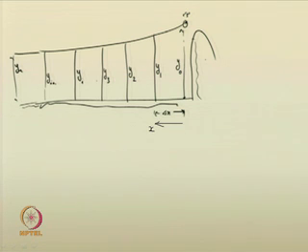So, if you discretize into such small reaches, then based on the known value, if you are proceeding into the unknown direction, this is called the step method. Your direct step method was also following the same procedure. Here also we will be first starting from a known value and then trying to compute the unknown values sequentially. So, that way one can proceed. This is called the step method.